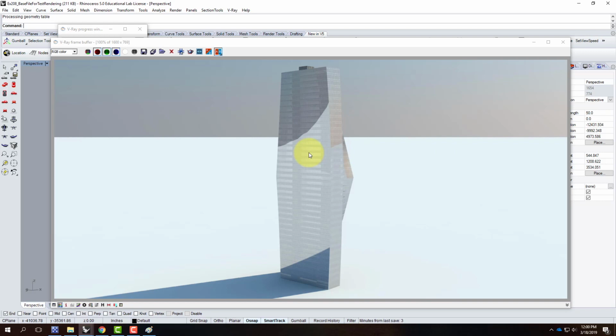Create your bulge, create your profile, twist it, that sort of thing. And when we go to do the unroll surface, you'll realize, oh, it doesn't work and it's not going to cut out right. In which case, you'll simplify it to do the unroll. You can still use the more complicated one for your 3D print and your renderings. You just can't do the unroll of it. So you'll simplify it, make it angular, and unroll that. But you could use a triangle or a hexagon or something that has straight edges on it. Absolutely, and you can twist that and have really good results.